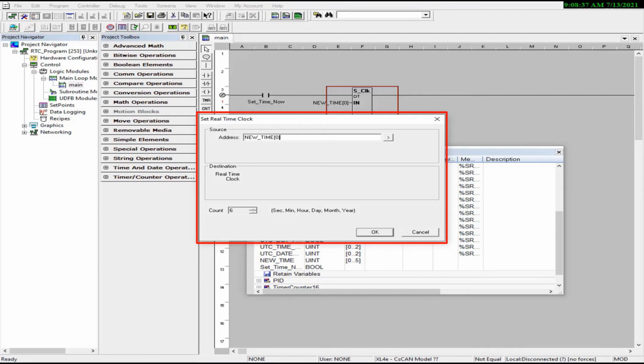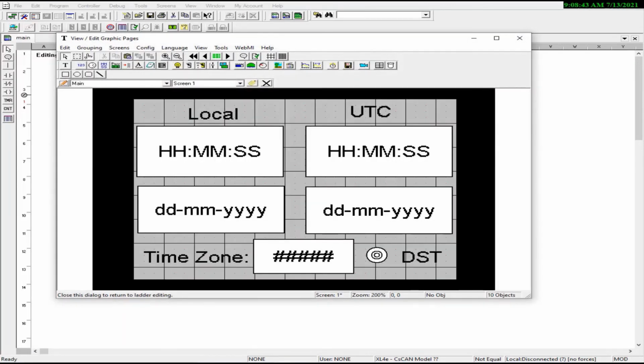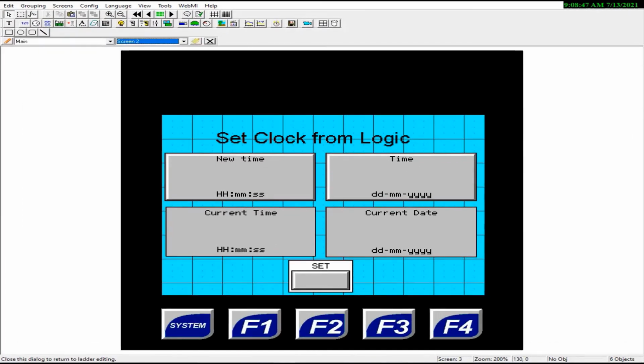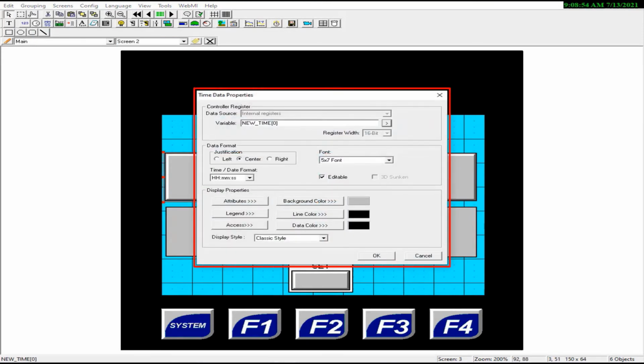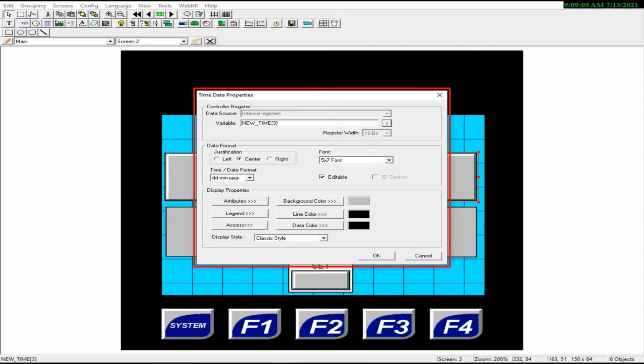to. Let's create a screen that gives the operator the ability to enter in a new time and a new date, and these utilize the time-date display objects. I'll double click here. We're talking about the time now. We're going to reference seconds, and seconds is the very first entry in this array of 6 objects. So it's important that we reference the appropriate member of that array. And then for date, we want to reference the 4th member of that array, because we have 3 that deal with time. So you can see number 3 is our index.